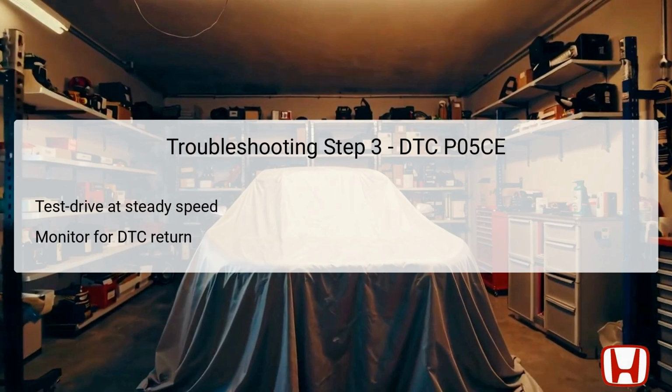After completing the test drive, it's essential to monitor the Honda Diagnostics System, HDS, for the reappearance of DTC P05CE. If the trouble code returns, it confirms that the malfunction persists, indicating that further inspections and repairs are necessary. Tracking these conditions helps to isolate the malfunction to either a temporary issue or an ongoing defect within the VTC system.